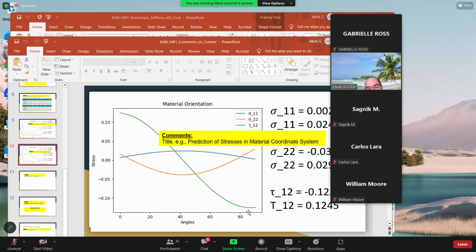So your conclusion would be, you don't need to make this conclusion, but after homework 3 with strength analysis, you would say, aha, I really want to have smaller stress, so my orientation would be somewhere here. Here we have smallest shear, relatively small transversal, and sigma 1 will be still about the same.